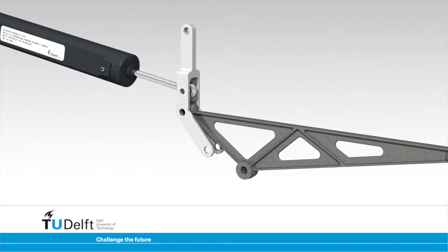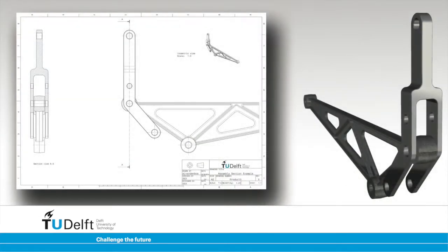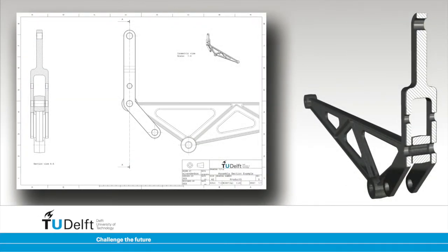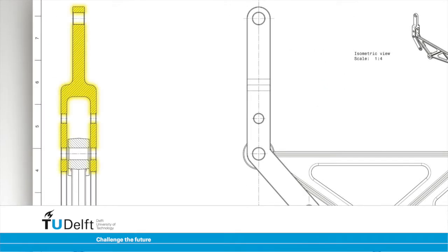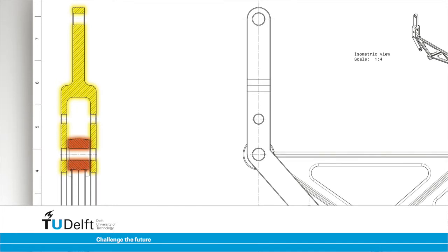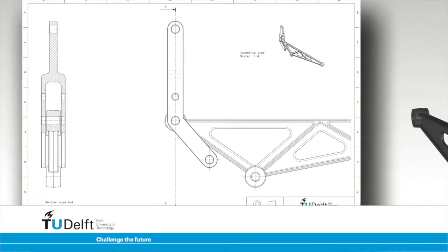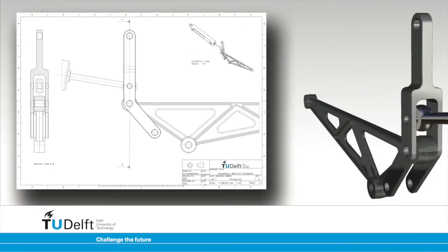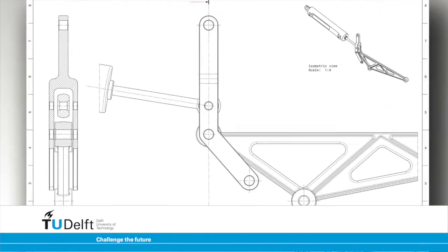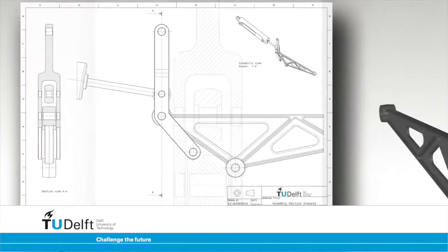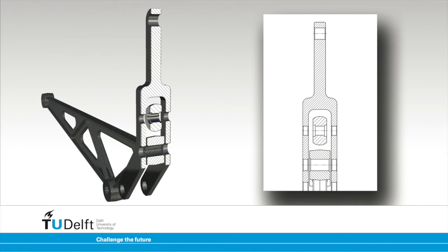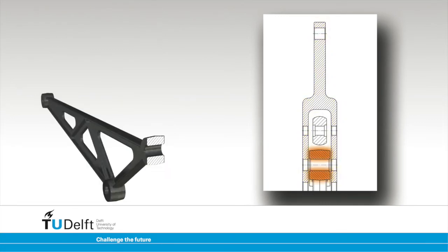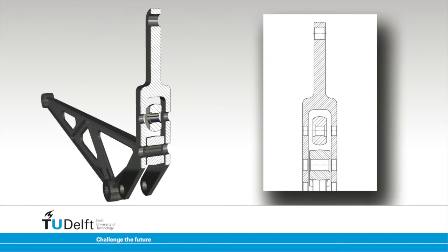Section views can also be used for assemblies. Make sure to use a different hatch pattern direction when two adjacent parts are sectioned. The preferred way to do this is to use a 45-degree angle for the first part and a 135-degree angle for the second. In a case where more than two parts are sectioned, the pitch between the hatch lines of one of the cut parts should be changed. If two areas in a drawing contain the same kind of hatching, this means that the two areas belong to the same part. Different hatching is used to indicate different parts.